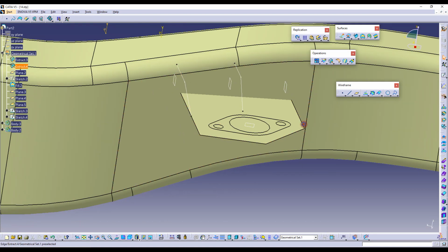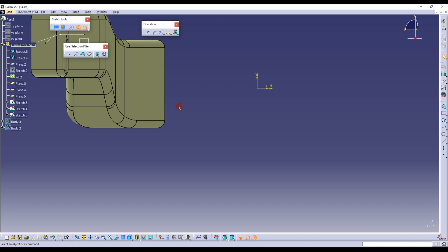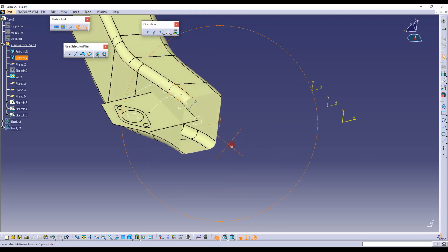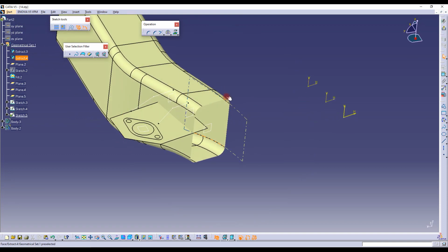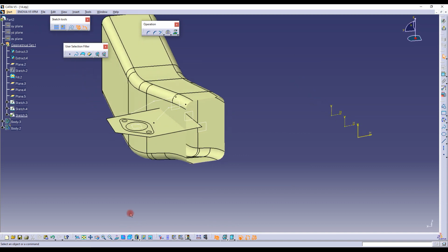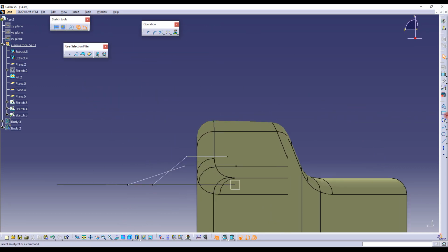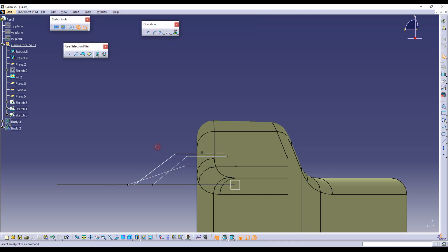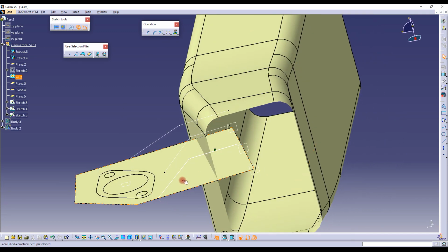Now we are going to sketch the third profile. So go to the third plane and go to sketch. Again, slice at the sketch plane, rotate to get a perspective, better understand the sketch, and make normal to sketch plane, and then start sketching. Start making the horizontal line and then the inclined line. So this line has to coincide with this.